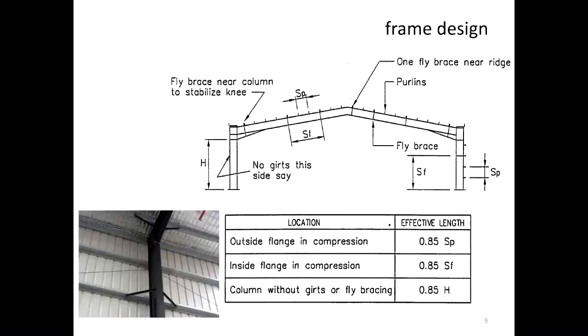And while it is a steel section, it will have a very, very high tensile strength. The compression capacity is not as high. So that is why the compressive ability or resistance has to be augmented to ensure that it provides enough capacity to resist the loads. Because the compressive capacity of the steel that is offered by the section is smaller, particularly for local buckling. So that is why we have to ensure we have all of these things.